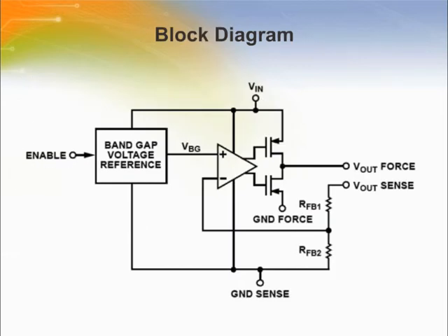Like all bandgap references, the ADR34 series references combine two voltages of opposite temperature coefficients to create an output voltage that is nearly independent of the ambient temperature. However, unlike traditional bandgap voltage references, the temperature-independent voltage of the references is arranged to be the base emitter voltage, VBE, of a bipolar transistor at room temperature, rather than the VBE extrapolated to 0 degrees Kelvin.